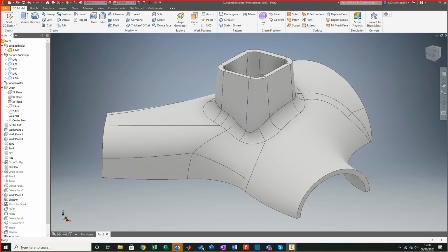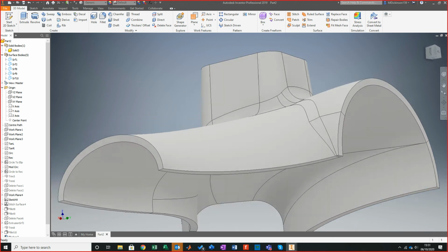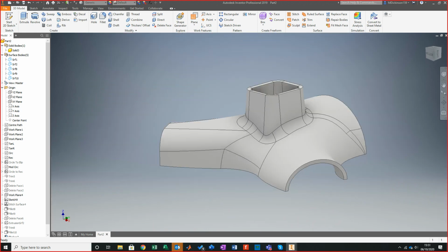Like me then, all I was trying to do is to particularly pick out the key problematic areas. Now I knew about the geometric interface, so I knew that everywhere where there was a key curve, there was going to be something going on. That's why I targeted this loft here, and I also started to target the fillets. One of them had to be responsible.